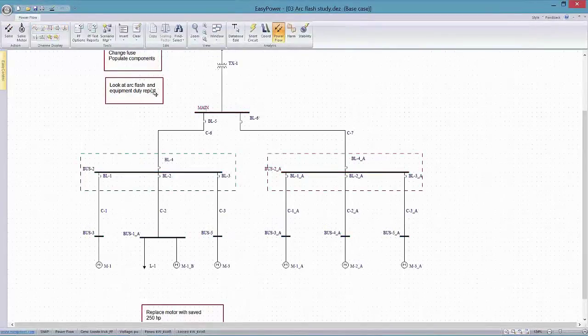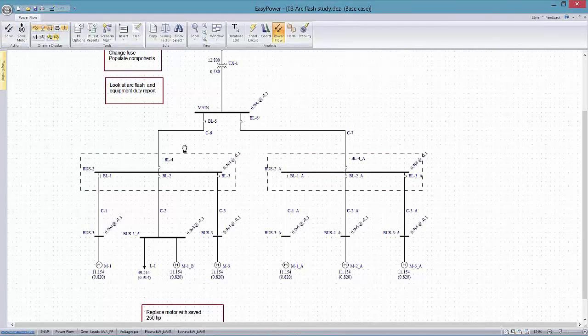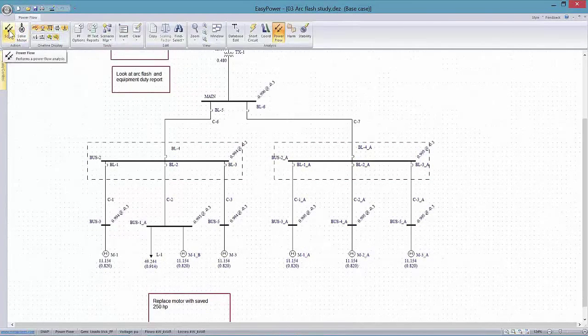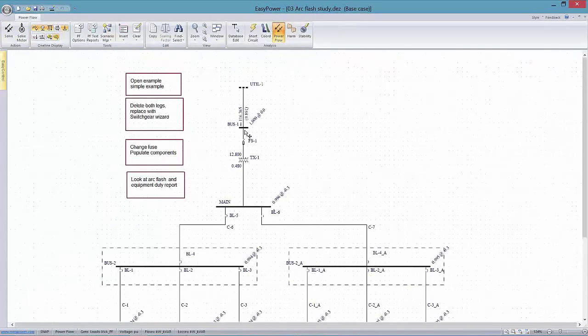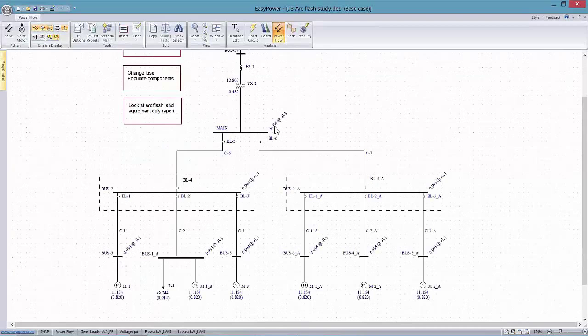All right. If we pick up the power flow module and do a quick study, we enter power flow, we solve, and we're able to display the voltages. This is saying that the utility is coming in at 1 per unit with a 0 phase angle. By the time it gets across the transformer, we've got a 0.996 per unit voltage and a slight shift in the power angle.